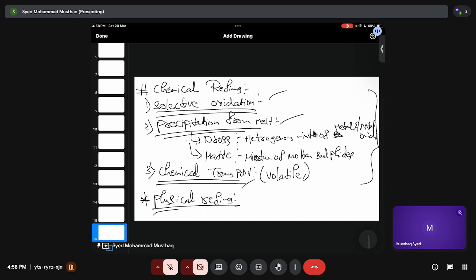And then we do the electro refining, just electrolytic refining. As I have said before, you take impure anode and then you take pure cathode, and you apply some electrical energy, and these copper ions will travel from anode to cathode, and the impurities will remain at the bottom. So they can be called slimes. Okay, and finally final refining, and again they are melted in an electric arc furnace, and they get cast into certain ingots or shapes.